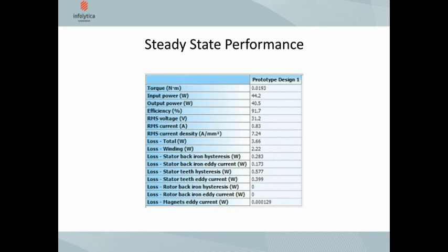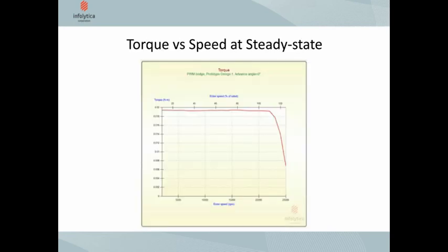We have less than 20 millinewton meters of torque, and so our criteria is not satisfied. And we can look at that through our torque speed curve and again verify that we're just under throughout the entire range. And so we need to make an adjustment because we no longer meet the requirement.